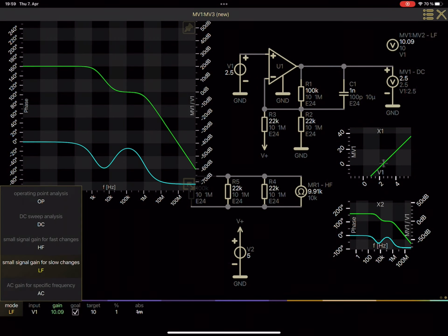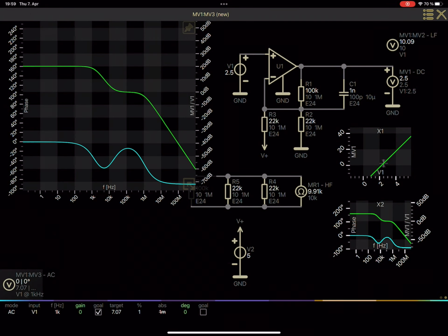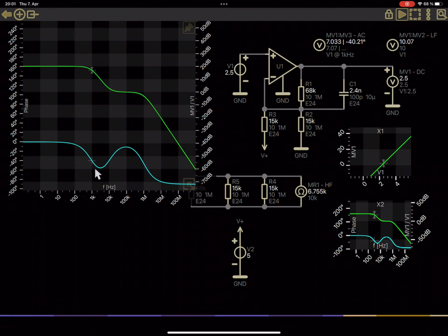At last, we take care to get a certain bandwidth limit for our circuit. Since the Bode plot shows an ambiguous phase curve, we are forced to use a gain design target to define a bandwidth limit.